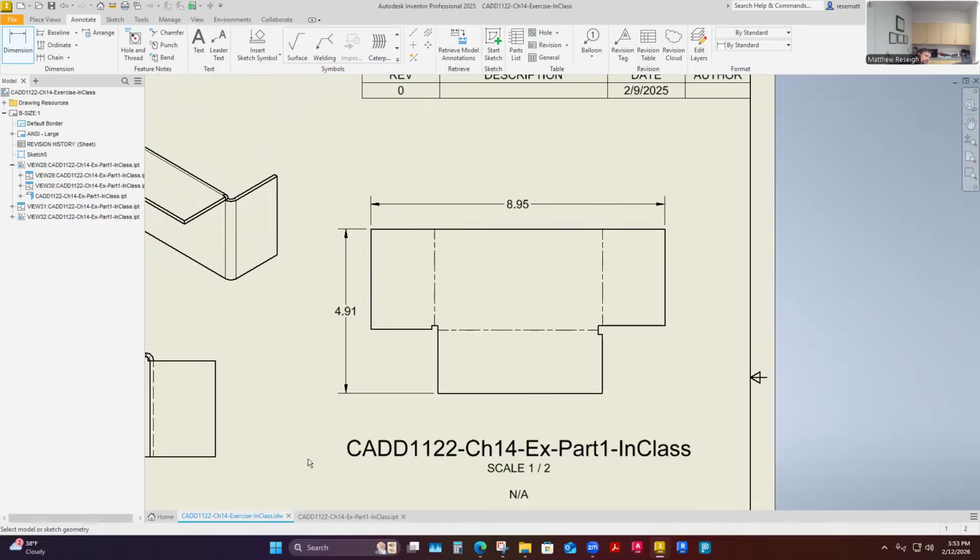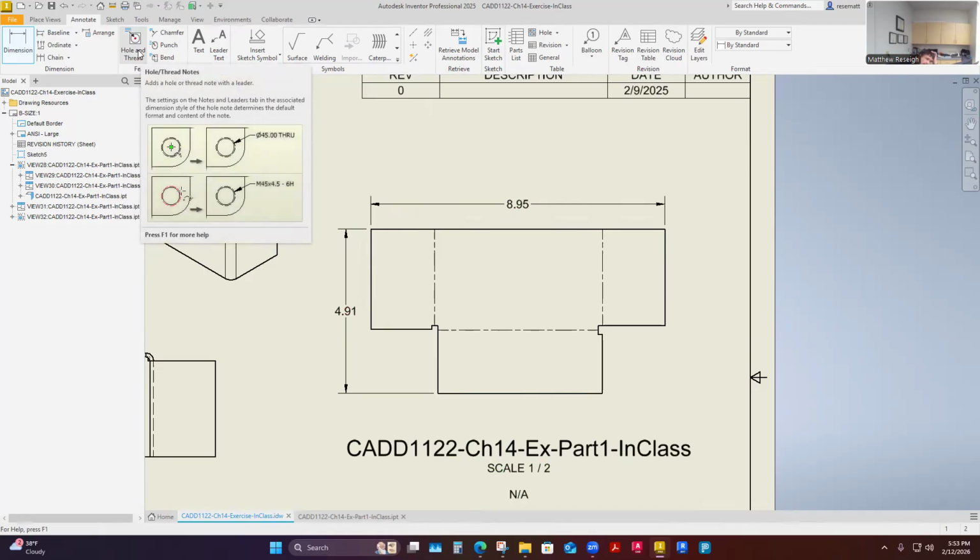Let's see. Yeah, I can do that quick. So on a cut file sheet, that might be all they need to know, just a quick part identification dimension. And then we have this, which is above and beyond what the chapter shows, but on my annotate tab, I have this where I pick when I have a counterbore on that last job. We use this to identify it and notate it really fast.